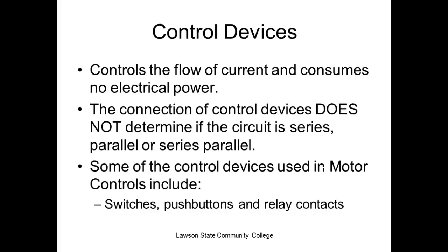A switch has no opposition. It does no work. It's got 0 ohms, right? So if you put your meter across a switch and you close it, your meter's going to go to 0. V is equal to I times R. If you have no R, you can put all kinds of current through it and you don't get any voltage. Now, the open switch, right here I would measure what? I measure the source voltage.